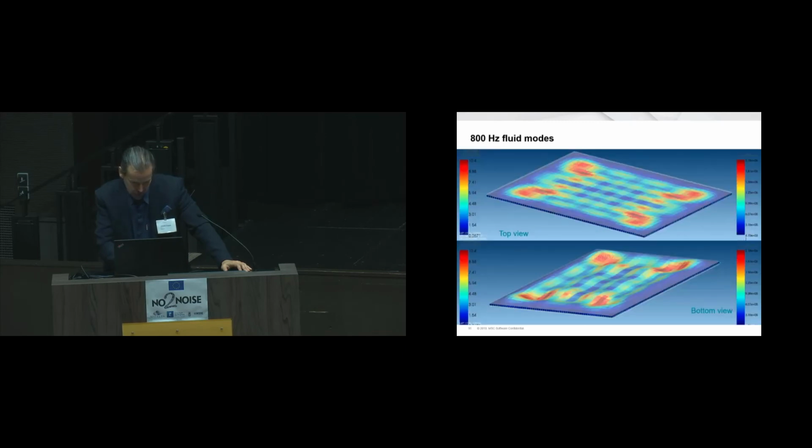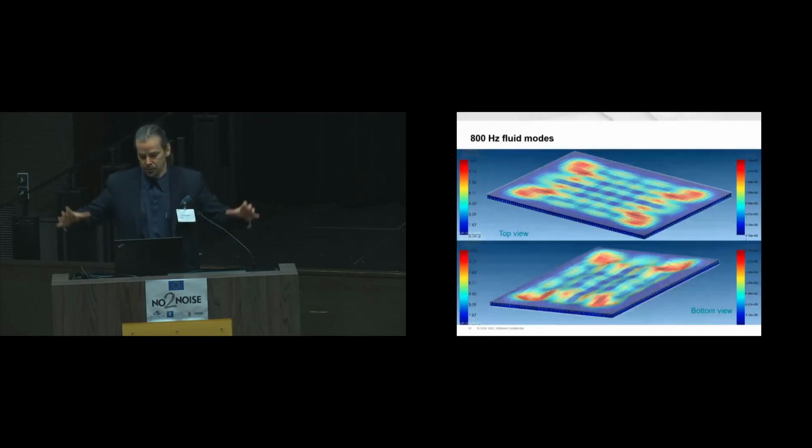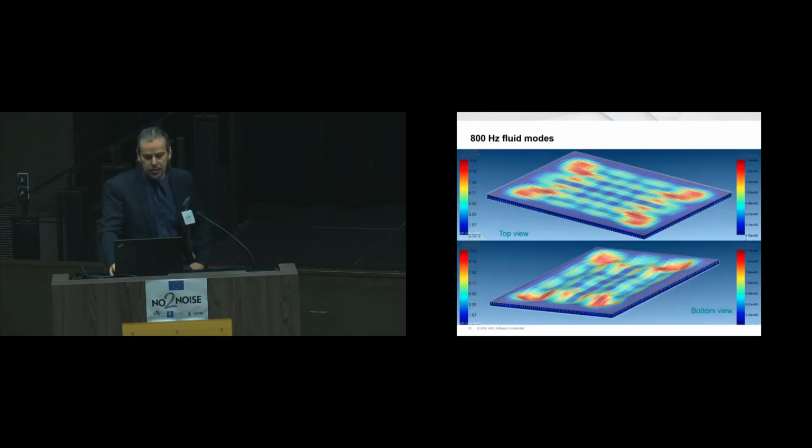Okay, some animation again. So you see that it's not modal, because damping is so high. It's more like you create waves at the boundary, and those waves propagate towards the center. That's really what's happening. Okay, so in this case, the infinite plate model will start to become a nice model again, because you still have a side effect, but even within the center of the plate, the decoupling is large, and you will model well the damping linked to the fluid motion.